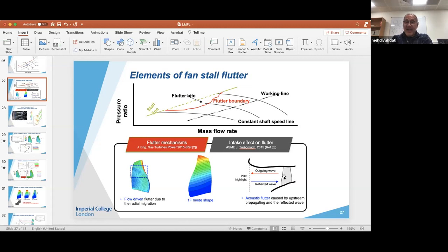And the reason the results I show here are quite decent is that over the years, while I was working with AU3D, we have tuned all the parameters in the turbulence model to be able to predict good mean flow for the fan blades that we are working on. So number one importance, in my opinion, is getting the turbulent mean flow correct, and getting turbulence modeling going correctly.